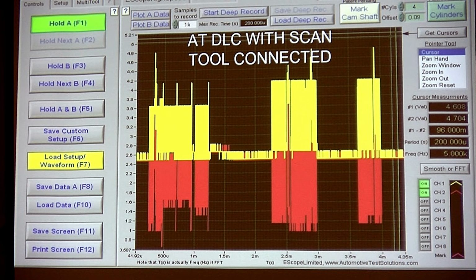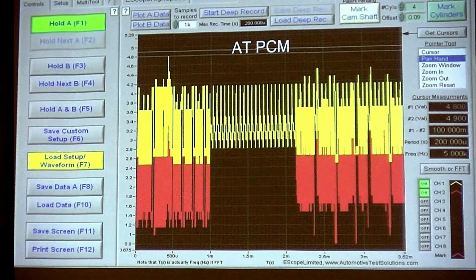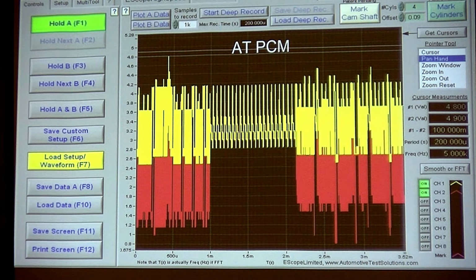Then I'm going to have to go do something else, so I'm going to find the easiest box, usually an ABS module or an engine control module, because those are the easiest ones under the hood for me to find. I'm just trying to make sure I'm in a real system here, right? And here we can see I have two totally different waveforms. So here, what I'm interested in is this problem that I see exhibited.